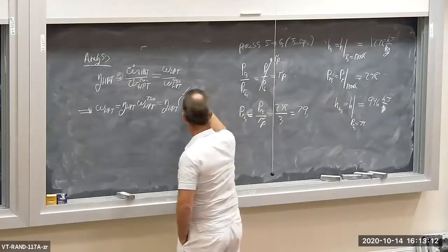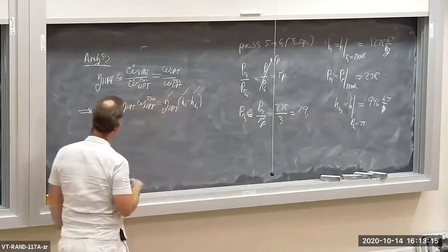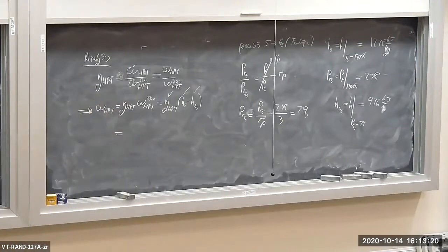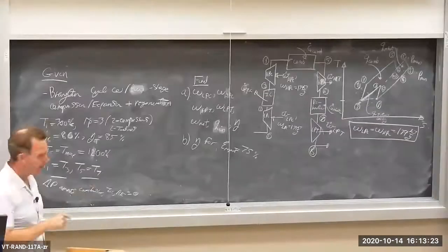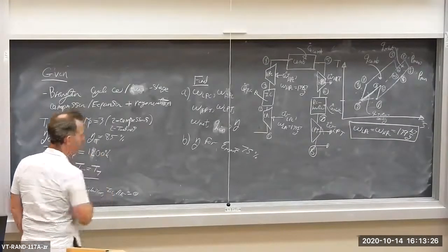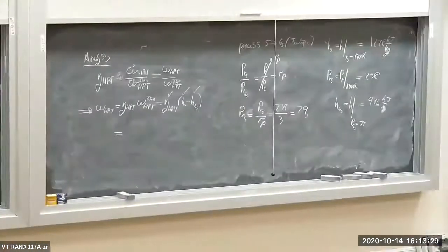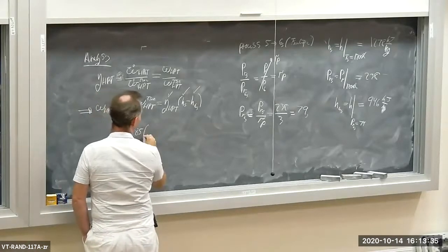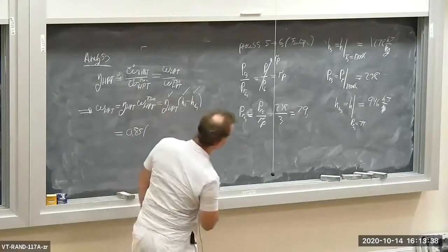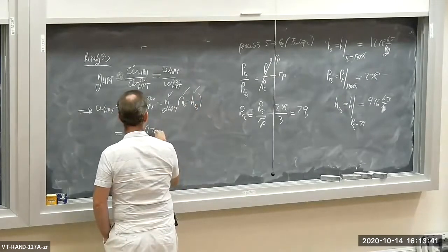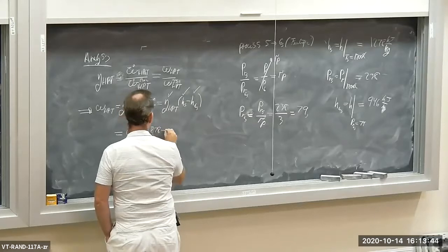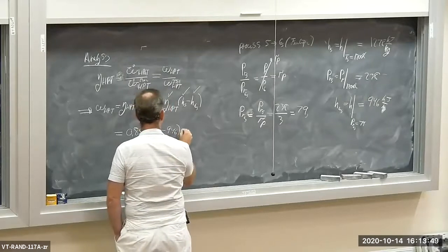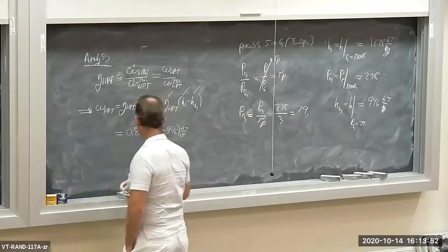Okay? So now I have H6 sub s, and I have the isentropic efficiency. Let me plug in. What's the efficiency of my turbine? The isentropic efficiency of each and every turbine is 85%, so 0.85. H5 is 1278 minus H6 sub s, 946 kilojoules per kilogram, times 0.85.